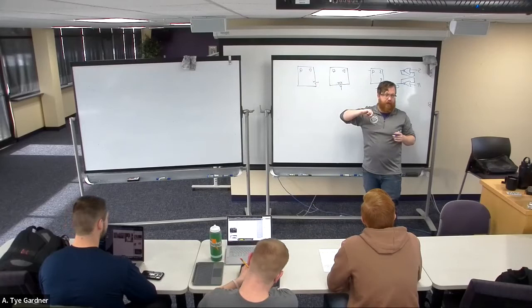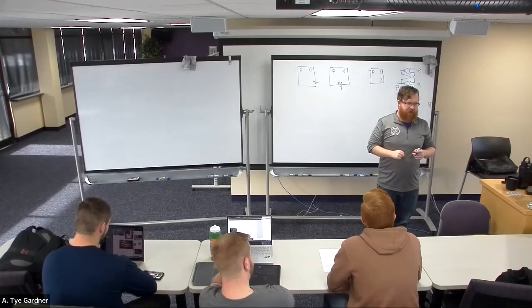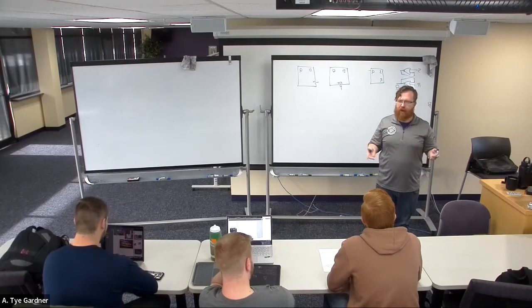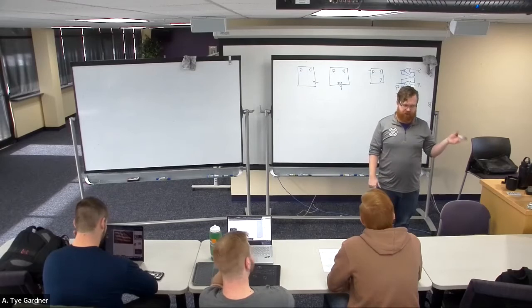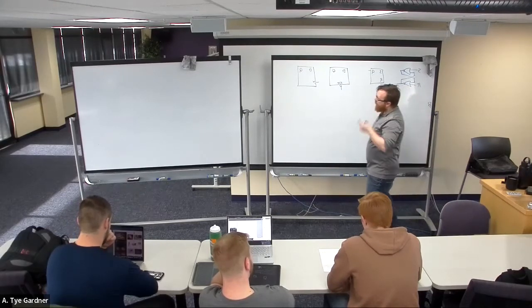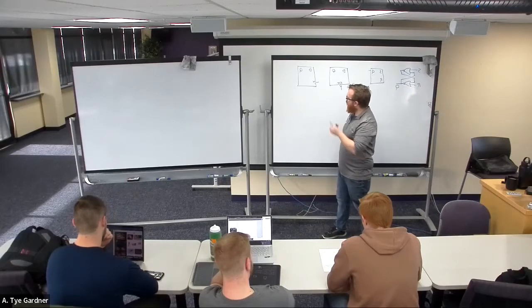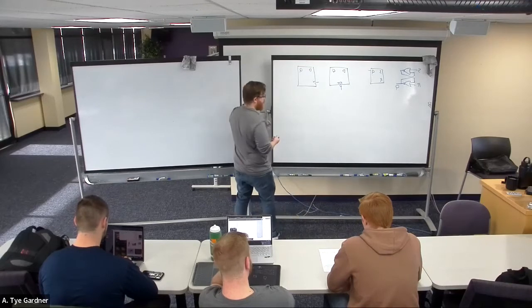And flip-flops are nice because now they give us the ability to synchronize our devices, right? Because the rising edge will happen at the same time across the whole device, and now the behaviors are synchronous. This makes synchronous logic.